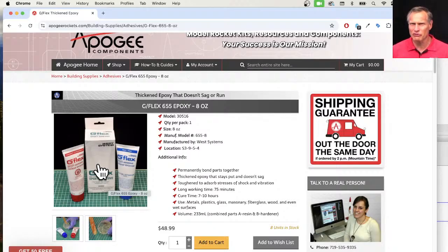It comes with a basic resin, and then there are different hardeners, a fast hardener and a slow hardener. I usually use the fast just because I'm impatient. Sometimes using the fast is not the thing to do. I was making fin fillets on a small rocket using the fast hardener, and it was hardening too fast, and I couldn't get the fillets on fast enough.